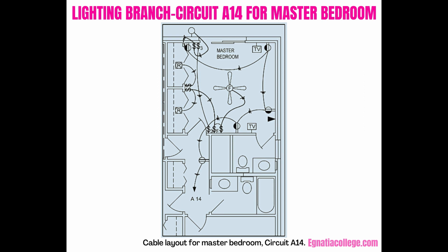Because there are 2 entrances to this room, the split-switched receptacle outlets are controlled by 2 3-way switches. 1 switch is located next to the sliding door. The use of split-switched receptacles offers the advantage of having switch control of one of the receptacles at a given outlet, while the other receptacle remains live at all times. Next to the door to the hall is the other 3-way switch plus the 2 single-pole switches for the ceiling outlet and fan.